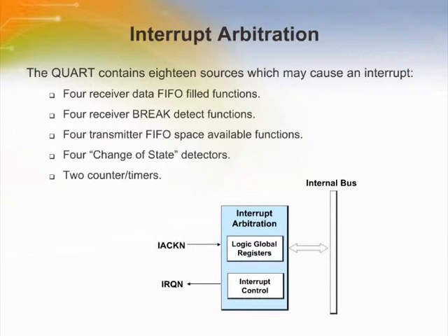The interrupt logic at each source produces a numeric code that identifies its interrupt priority condition currently pending. The code contains the identity of the source, channel number, and severity level. This code is compared to an interrupt threshold. When the interrupting source generates a code that is numerically greater than the interrupt threshold, the IRQN is asserted.